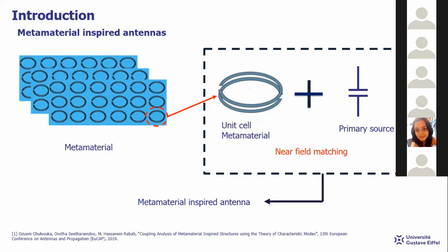When we combine these metamaterials as parasitic elements with a dipole in the near field region, we can have energy compensation and enhancement, and this leads to the concept of metamaterial-inspired antennas. However, classical metamaterials cannot lead to circular polarization.